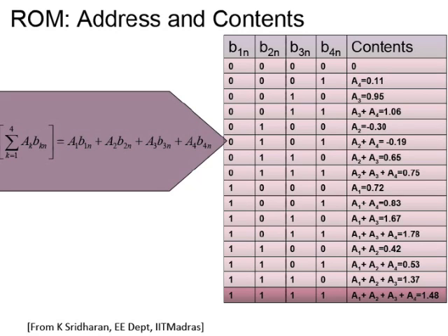For example, you take an inverter and you put the 0 at the input of the inverter. You look at the output of the inverter. Output of the inverter will be 1. There is leakage, but it will be held 1 because the input you have kept as 0. So that's how, even though there is leakage, the output is held to be 1.